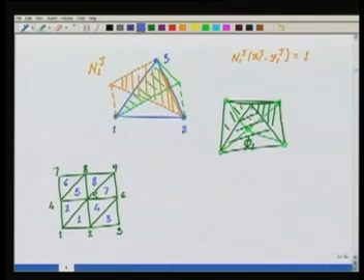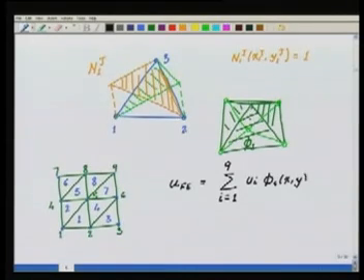So now I will have how many basis functions formed by piecing together these piecewise linears? I will have 9 basis functions corresponding to the 9 nodes of the mesh. Okay. So now if I want to make a global finite element solution which is a linear approximation over this domain, then my UFE would be equal to the sum of I is equal to 1 to 9 UI phi I, which is a function of x and y.